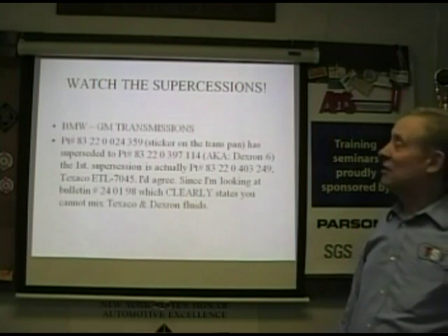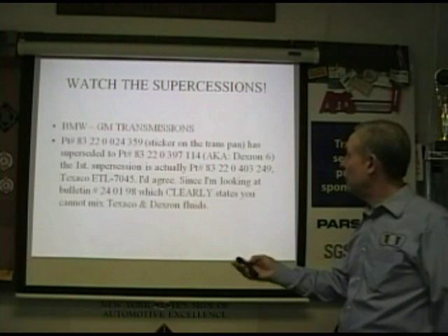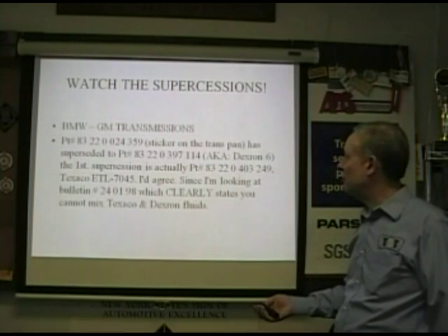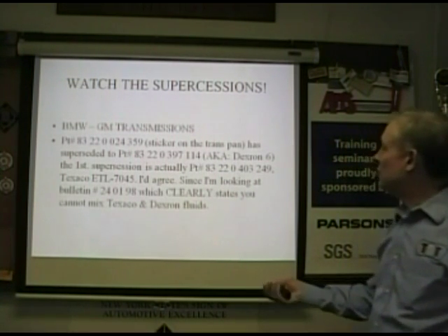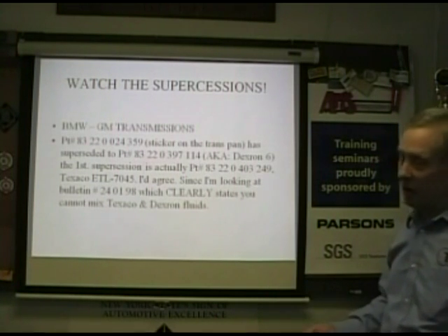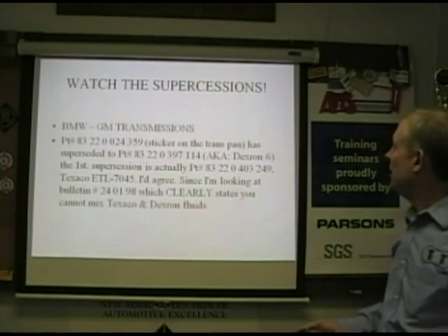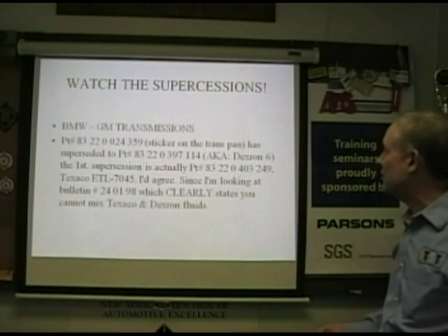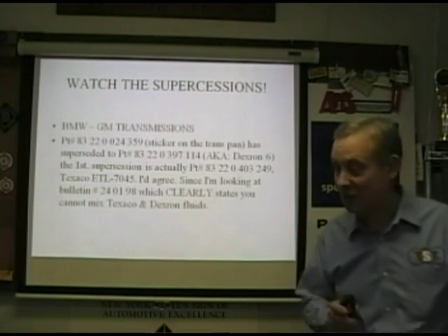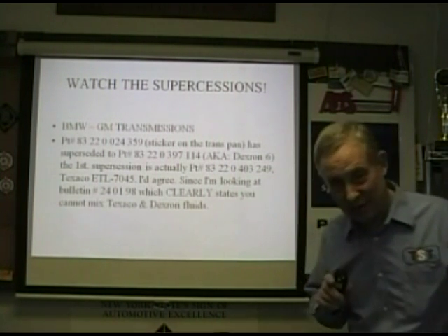BMW, GM transmissions. This is something you should be aware of. There's a sticker on the transmission with a BMW part number. It says it's incompatible with Dexron, and yet you can use Dexron.